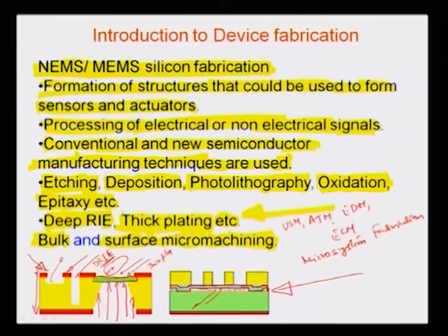So, you can remove away this resist, later on it just goes off, thus resulting in this channel into the plane of the paper or plane of this transparency slide. So, this is an example of surface micro machining or additive micro machining.